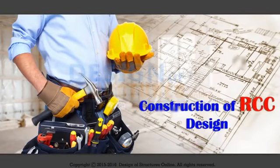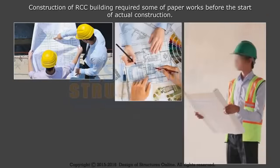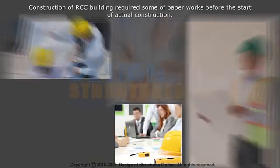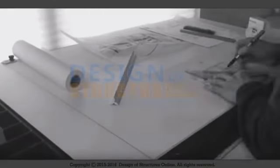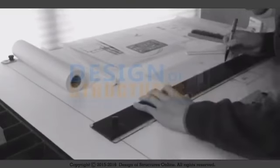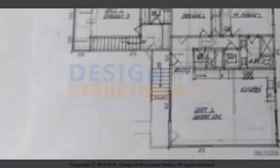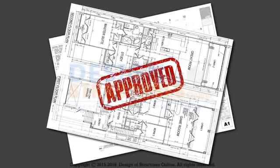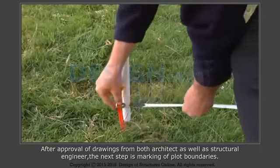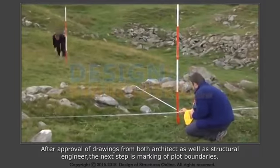Construction of RCC building. Construction of an RCC building requires some paperwork before the start of actual construction. The very first stage is preparation of drawings as per requirements of the client. Once drawings are completed, approval of drawings is important. After approval of drawings from both the architect as well as the structural engineer, the next step is marking of plot boundaries.